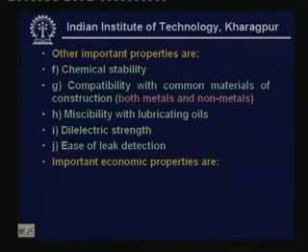Okay. There are various methods of detecting leak of a refrigerant. For example, if you are using ammonia, then you do not need anything, because your nose itself is the best leak detector, because ammonia has a very strong odor. So immediately you know that it has leaked out. On the other hand, some of the refrigerants such as R12, R134a, etc., you have to use some special leak detectors, like halide detectors or electronic leak detectors, to detect the leak. Okay. So this is again an important practical requirement.